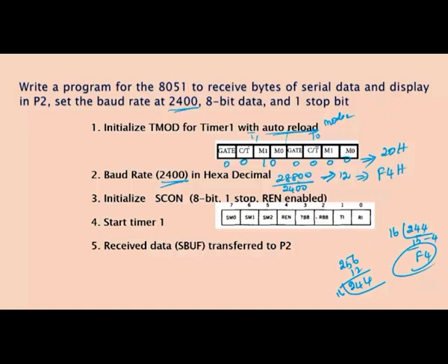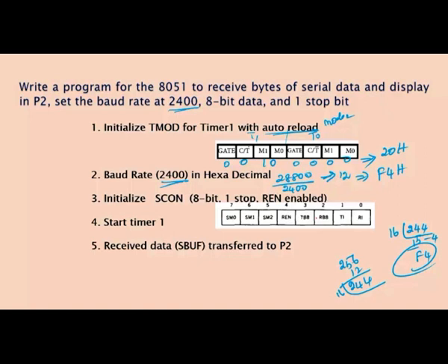Okay. So, already we know how to calculate the baud rate 28,800: the system clock divided by 12, again divided by 32. So I used this. From that the given specified baud rate is divided, you will get 12, then it is subtracted from 256 to convert into the number, because it is an 8-bit register, the maximum value minus only we are giving.